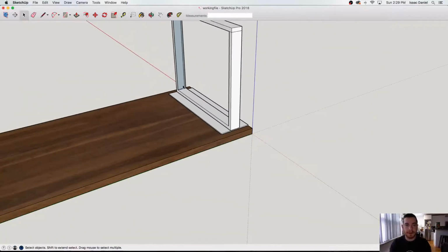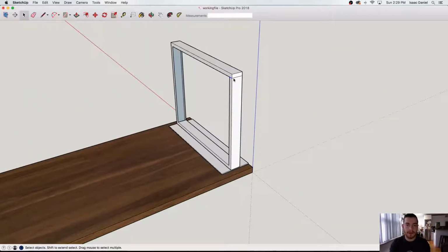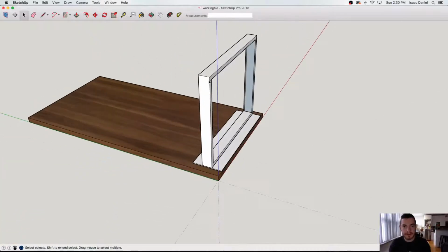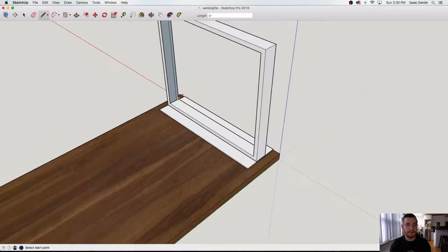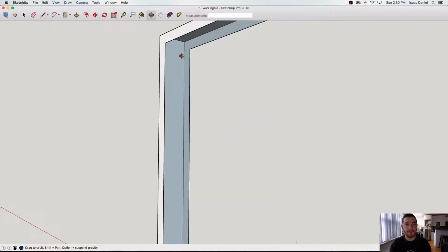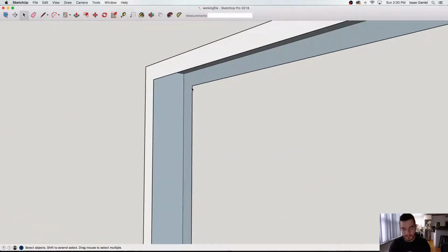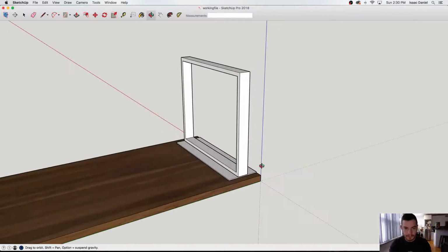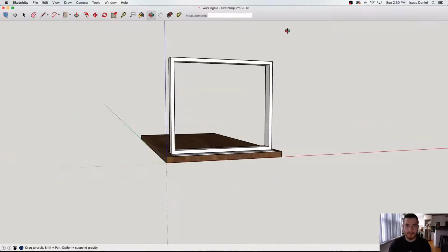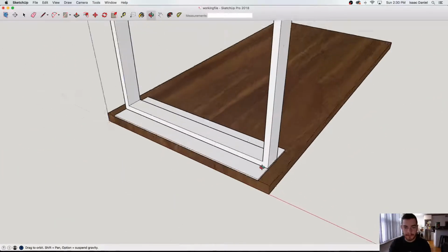And you can see from rotating it, we have another face that we lost in this case from the way that we made that side. So we'll just go back and draw that line back in there, and SketchUp will eventually figure out what's going on. Maybe it's not that line, it's this line. So you can see it's missing this line here, so SketchUp doesn't know what to do in this area. So we'll draw it back in, and you've got your faces back. So there you go. You've got a pretty standard U-shaped leg.